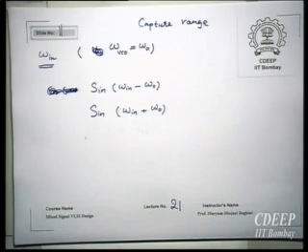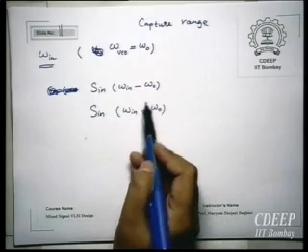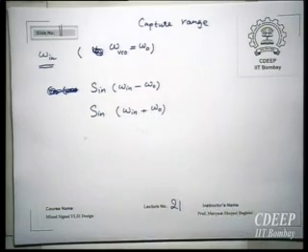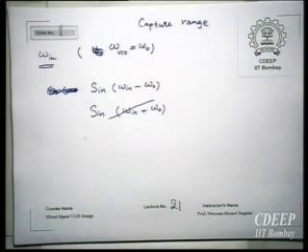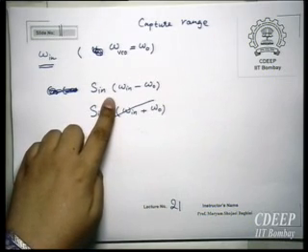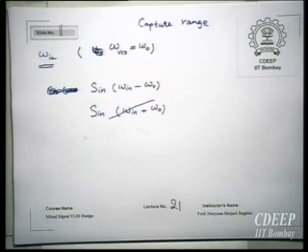Now this is given to the charge pump. Charge pump is essentially a low pass filter, and therefore it will attenuate both of them. First of all, suppose this will be attenuated in such a way it is almost negligible. Therefore, I don't care about this term. What is important is this term, right? So now this term comes to the low pass filter, which will attenuate it. So what will be the output of this? I have now a new frequency, right?